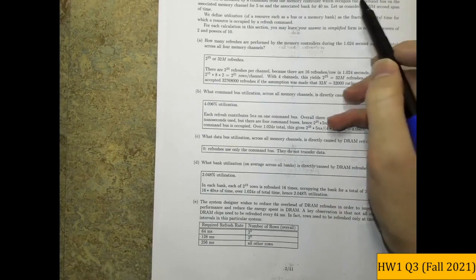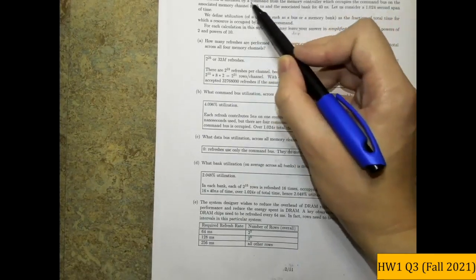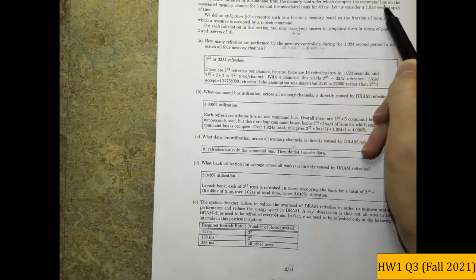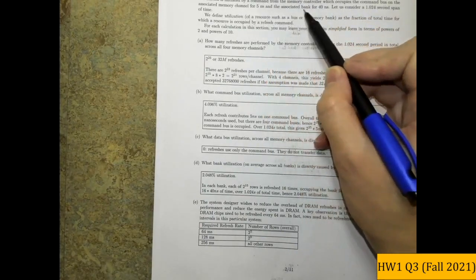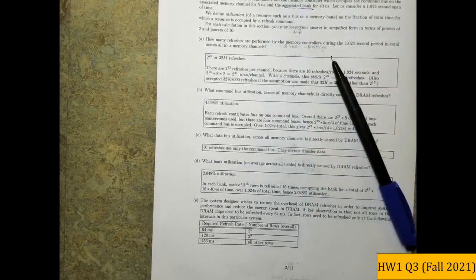So let's see what it says here in the question. DRAM is refreshed every 64 milliseconds, running by command from the memory controller, which occupies the command bus on the associated memory channel and the associated bank. So a single refresh command will only refresh a single bank from that rank, right?